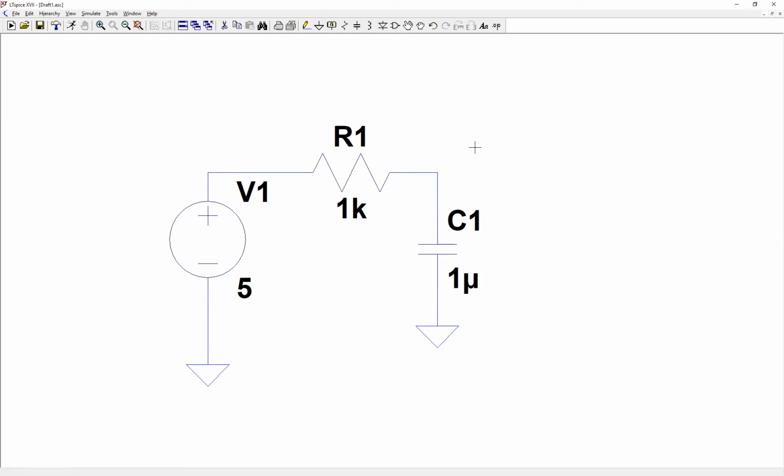Finally, we want to measure the voltage across the capacitance. This can be done also like this, but I definitely usually suggest putting labels. So when we plot the waveform, the waveform will have a name, and it is easy to understand which waveform we are talking about. But again, I won't do this now, so you can see why we need a label. I will show you how to add the label later on. But this setup is sufficient for doing what I want.